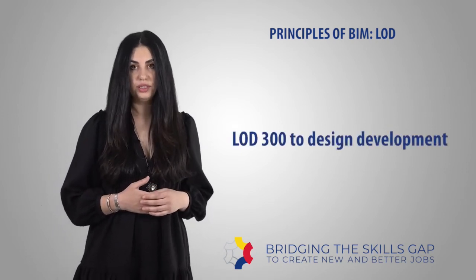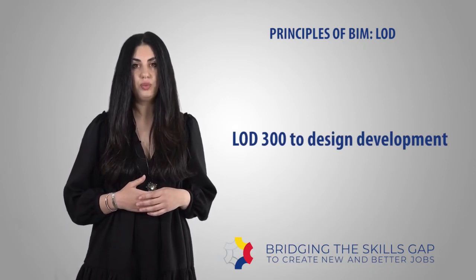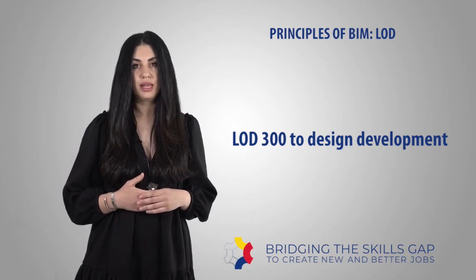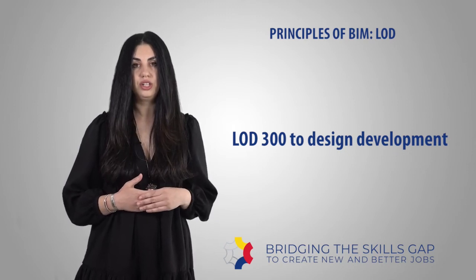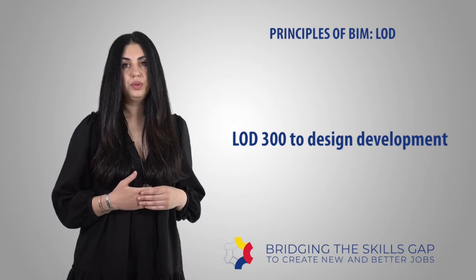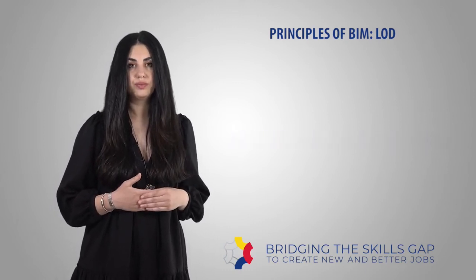LOD 300 is a detailed design, accurate modeling and shop drawings, where elements are defined with specific assemblies, precise quantity, size, shape, location, and orientation. Here, too, we can attach non-geometric information to the model elements.